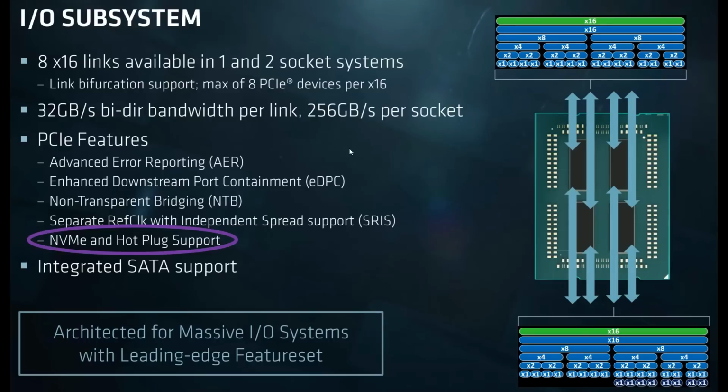Flipping over to the AMD side, you'll see that each EPYC die has a series of PCIe lanes. Some of them are used for Infinity Fabric, which are these green ones, but this depiction down here is actually SATA lanes. So if you want to use SATA, you have to actually take PCIe lanes out of your 128 PCIe lane pool in a dual socket AMD EPYC configuration and reconfigure them for SATA usage or for your BMC. There's a number of uses.